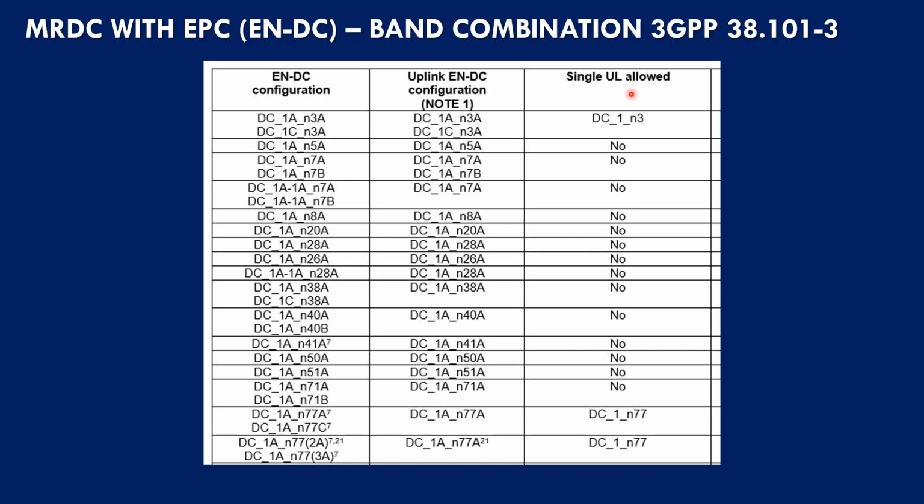We know that this is done to remove the possibility of intermodulation interference. When LTE and NR transmissions collide, simultaneous dual transmission may not be supported by the UE for these ENDC band combinations, for which only single switched uplink is supported.